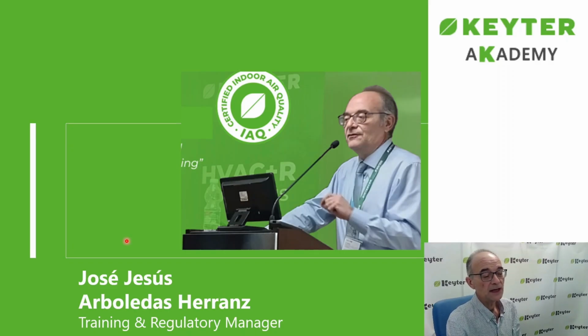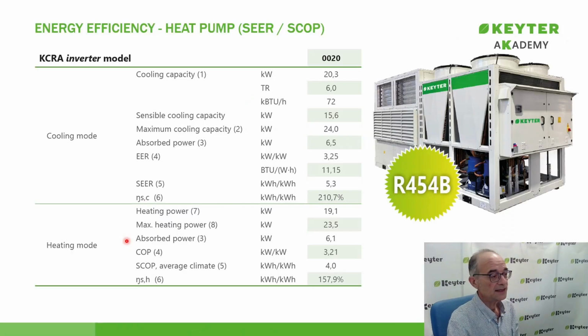And to carry out this study, the first thing we're going to do is take a specification sheet for a heat pump. In this case, we're going to take a rooftop unit, and looking at its specifications, we quickly come across this concept of SEER, operating in cooling mode. This concept of SEER has a note, which is note 5, and you should always read it when you have a specification sheet, since it defines the environment in which these parameters will apply.